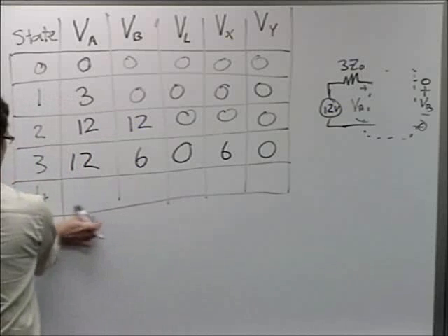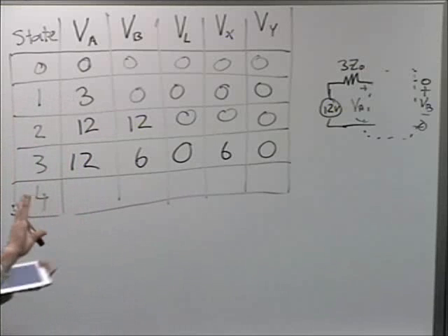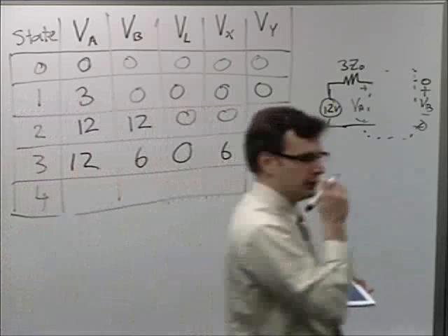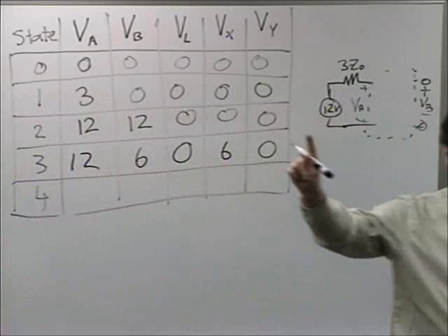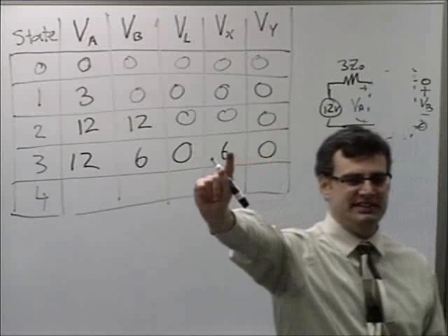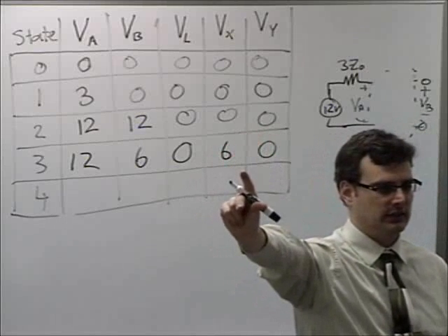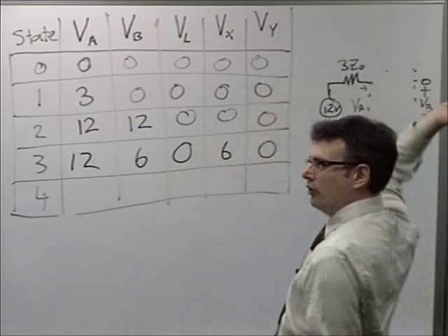That's good because you don't get double jeopardy, right? You'll make an error up here and then lose all the problem points later on. So, okay, let's do that last state. Now, all the switches have been closed for a long time. The capacitor, as it's charged to a DC steady state, becomes a what? Open circuit. So we can remove it from the equation.